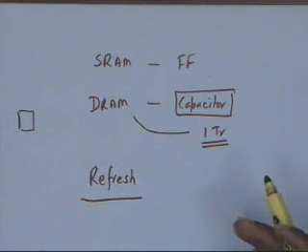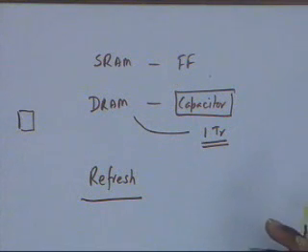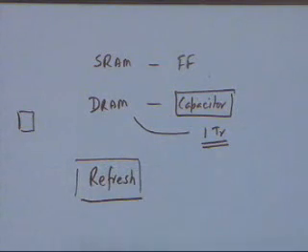So as far as the user is concerned, the refresh may be hidden, but a user may be forced to access at least one location in a certain block. There are considerable variations to this, but refresh is an important part, and only then does the DRAM work properly, if you are refreshing the cell which holds the data.